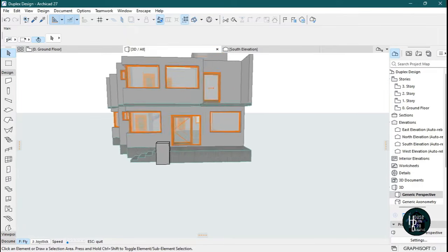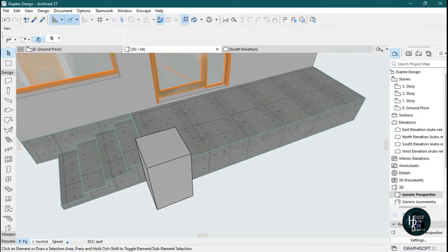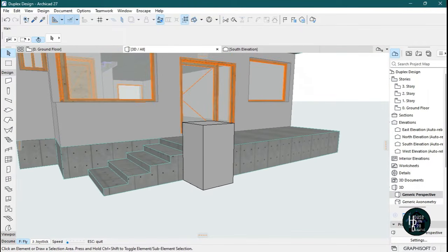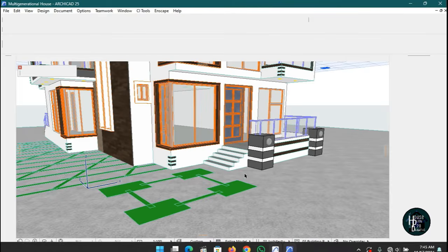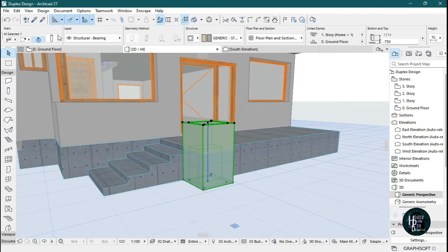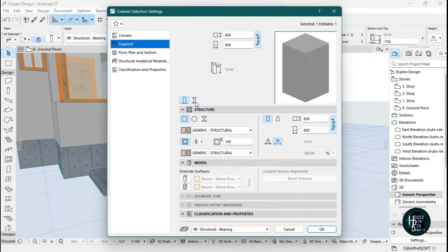As you can see, the next thing I want us to do is place 2 pillars here. I want to try and edit this pillar so it looks something like what we have here. For me to do that, I'm going to click on those pillars, click on the settings dialog, and click create segment. By clicking on the segments column, click multi-segmented and just press add. It's just like splitting the pillar into several parts.